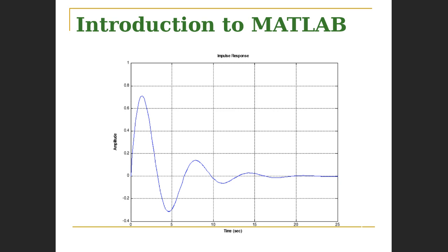0.7 meters. Again, this is based on what the math is saying. All right, 0.6 meters extended by 0.6 meters takes roughly about 2 seconds to get to that maximum point, and it oscillates for a couple of cycles, and then it finally settles back down to where it was initially after nearly about 20 seconds. So we could say that the mass, remember our output in the system is the mass displacement. So what we're actually seeing is what happens to the mass displacement over time.